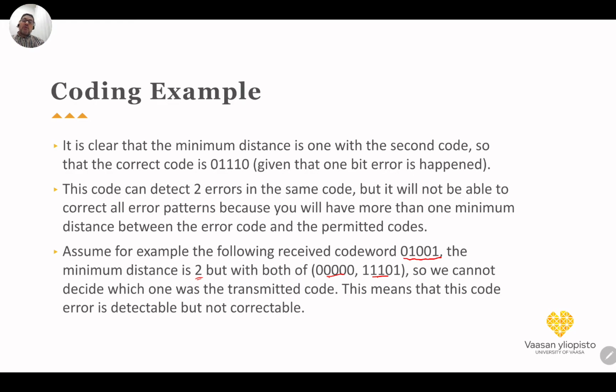There's another method for decoding, because this decoding is what is called a hard decoder. Actually, we don't receive the signal as exactly 0 and 1, we receive some soft value. For example, if the signal is between 0 volt and 1 volt, then we can have a threshold if the signal is equally likely, and we say that any signal less than 0.5 is 0 and any signal more than 0.5 is 1. This is called a hard decoder.